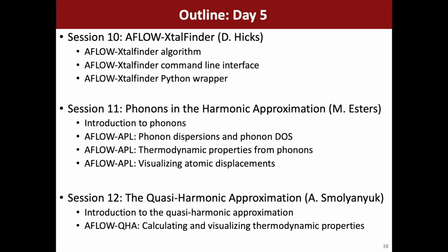Then the all AFLOW search includes, as well as the ICSD, the ones we know exist, hypothetical materials that are generated by decorating these structural prototypes. These are materials that we don't know if they're going to exist or not. This is where we do the thermodynamic analysis, and we try to predict what materials will exist. We can also combine groups of materials to predict things like the formation of disordered materials, although we won't be going into detail on that in this session, but it's work we've done in the past.